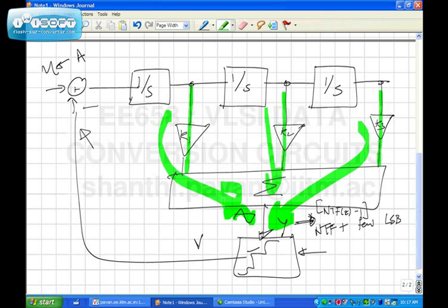And of course, the quantization noise you can think of as getting filtered through 3 integrators here. So the output at the third integrator will predominantly consist of the input signal plus quantization noise which has been filtered through 3 integrators. On the other hand, this one will consist of a smaller portion of the signal plus quantization noise which has been filtered to a smaller extent.